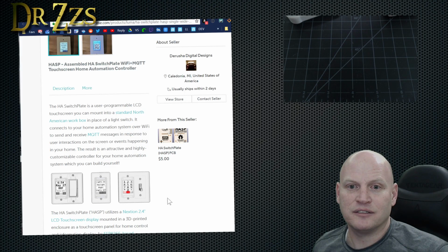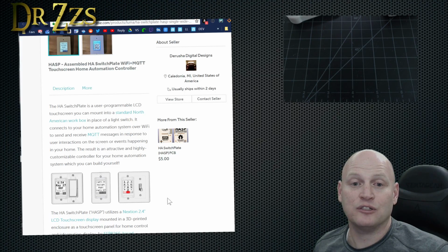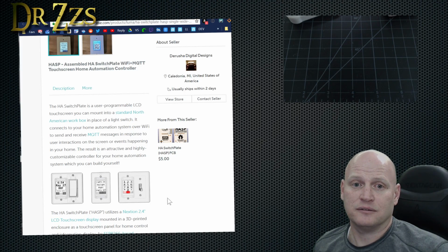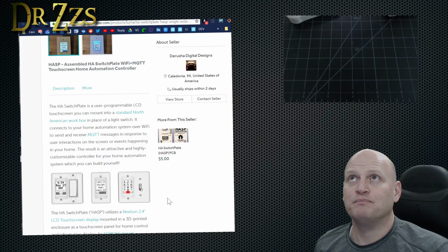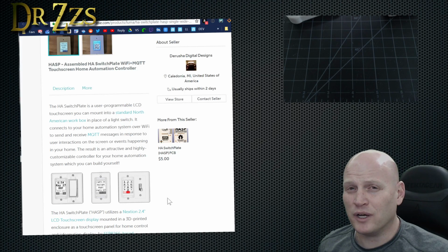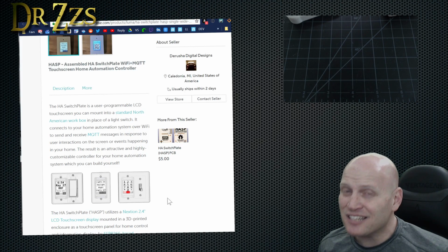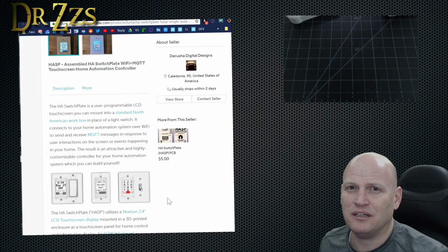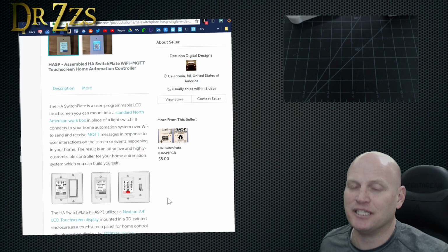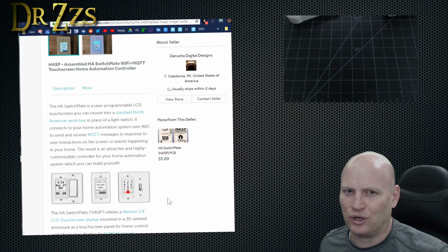Does anyone know if after flashing Sonoff T1 with Tasmota, it still works? Yes, it should, Jack. I haven't done it, but it should still work. If you have the RF bridge and you open the RF bridge and then push one of the buttons on your T1, you should hear a chime. If you hold the button, you should hear a chime. And then I think you'll see a message in the console of your RF bridge if it's also Tasmotized. Hopefully I'm not leading you astray. I haven't done that, but that's how I understand it should work.